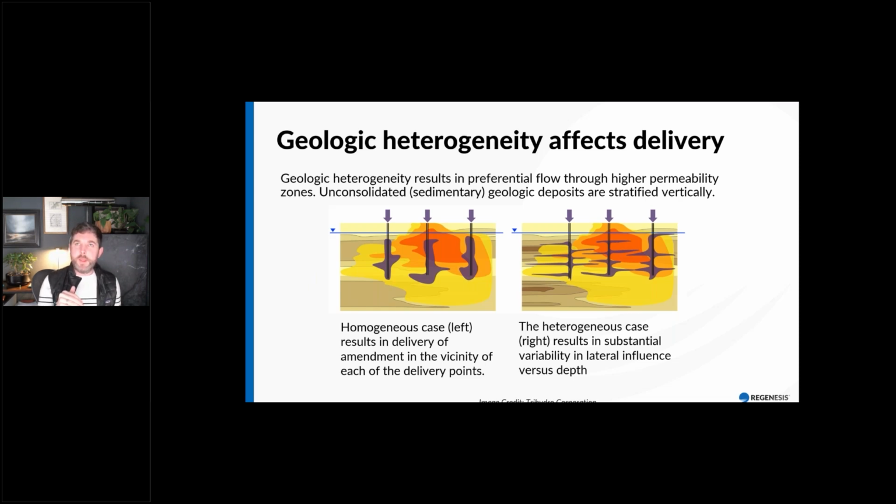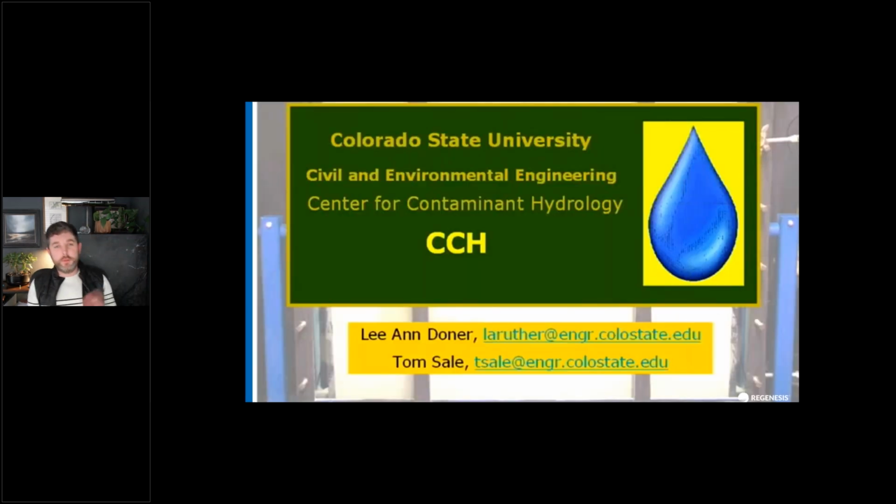And this is really important when you're looking at remediating chlorinated solvents, where typically we might be looking to reduce concentrations to parts per billion. And if we're looking at remediating PFAS, we have remedial targets at parts per trillion. Now, why this is important is all because of back diffusion. I don't explain back diffusion particularly well, but about 20 years ago, a sand tank experiment at the University of Colorado was done that does it quite well for me.